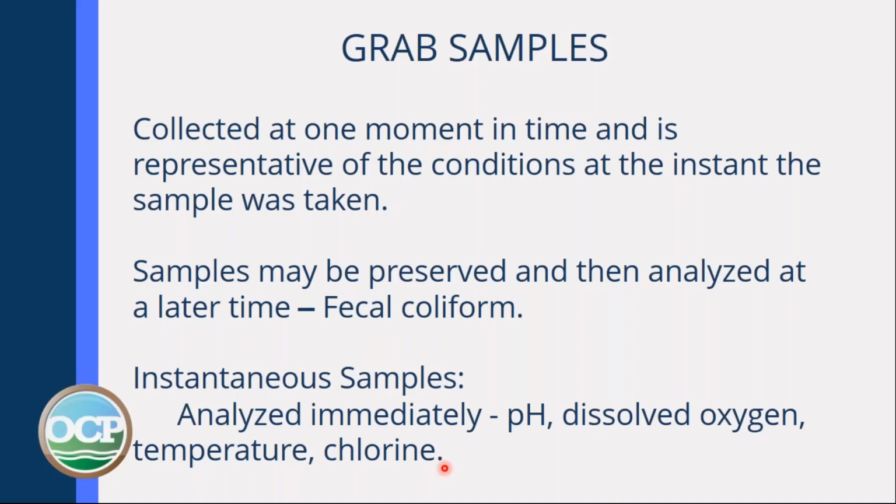So grab samples are collected at one moment in time. They're only going to tell you what's going on at that point in time, not earlier or later. You're either going to preserve them and analyze them later, usually in a lab, or you're going to have an immediate response reading of the water sample as you take it.